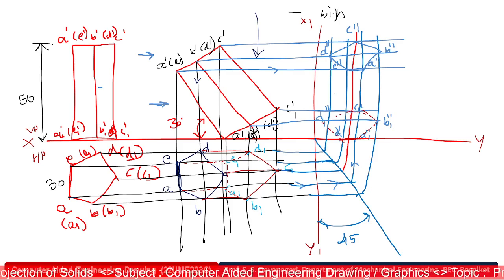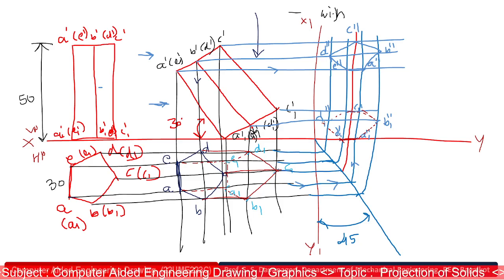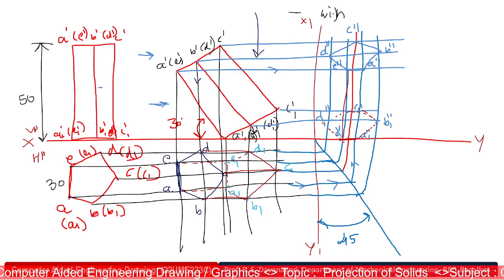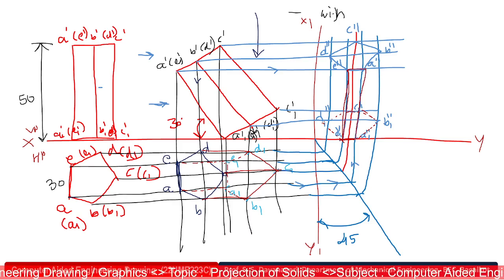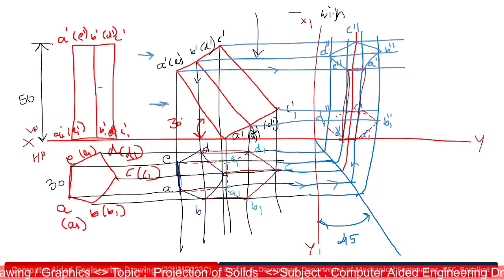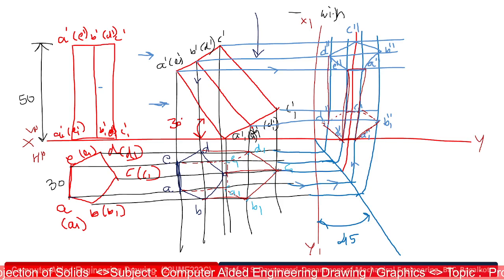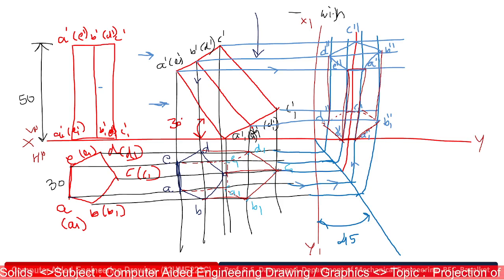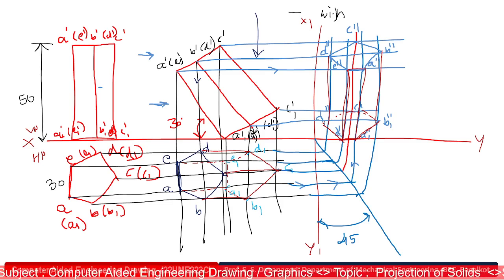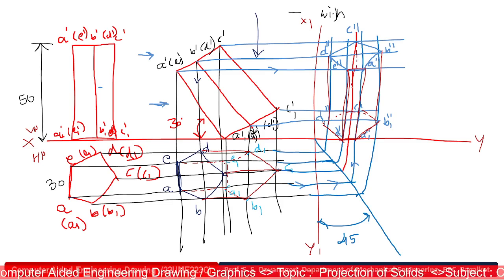Okay. So this rectangular surface is clearly visible. That is what. So now this surface is also visible. Sorry, this edge is also visible. Now the visible edges are here. So the only hidden long edge is C1 double dash, C double dash.